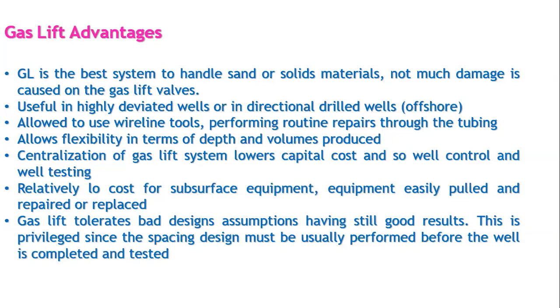Another point is that it allows flexibility in terms of depth and volume to be produced. Of course, once the optimum gas depth is defined, the conditions of the well and our reservoir are changing. So at some moment we have to go back and redesign, trying to get the injection point a little bit deeper to continue producing an optimum volume.